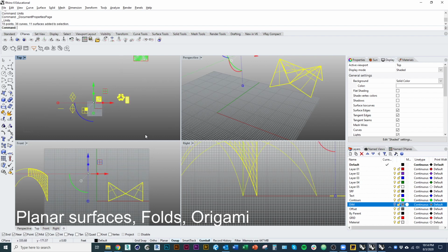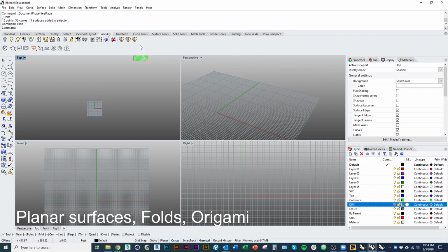In case you didn't know, a really good tip for navigating in Rhino is that you can hide and show things. If you go to this tab up here where it says visibility, and I'm going to use the command hide right now, so everything I had selected just then is hidden. So I'm going to introduce planar surfaces first.